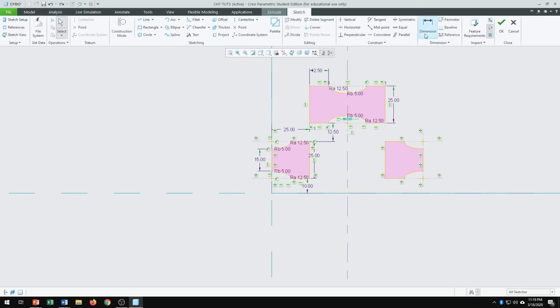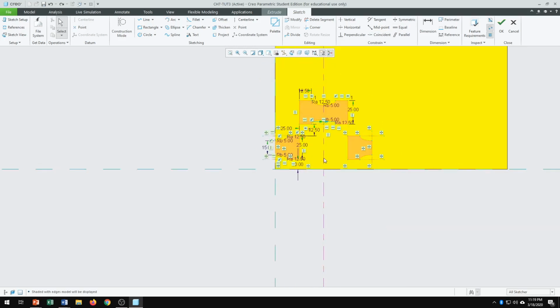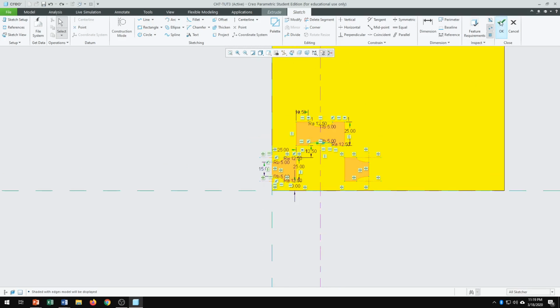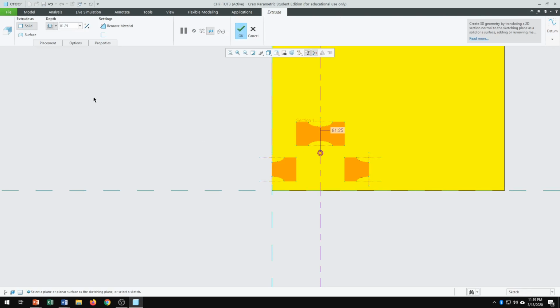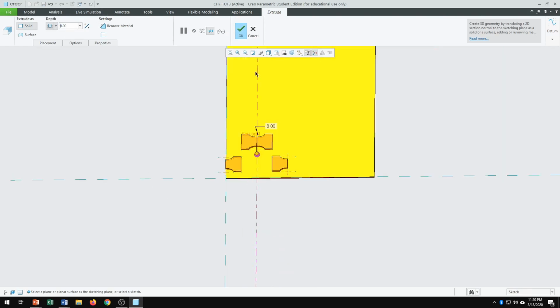And then let me go to coincident to see. So I want this to coincide with that. It doesn't matter. We are ready to go. Let me turn the shade back on. So we got this portion of the thread right there, and then we say extrude. We give the amount of extrude 8. We're going to give 8. Perfect. So we have that, and we say okay.